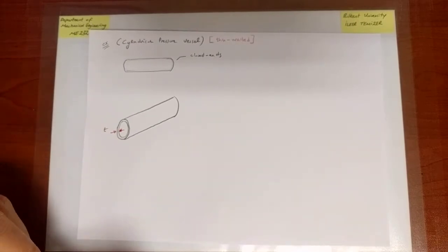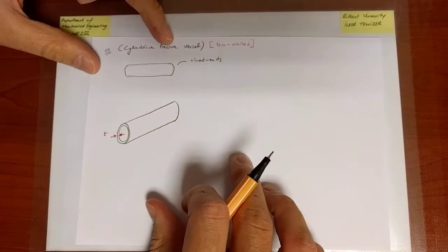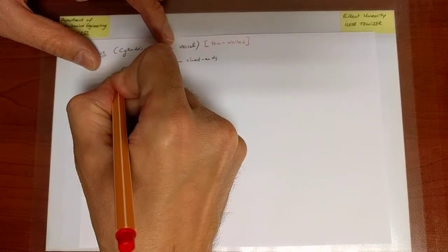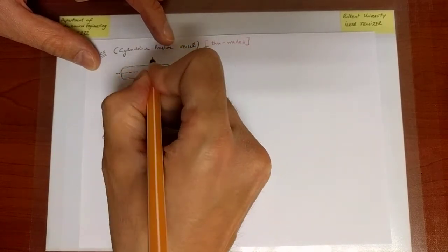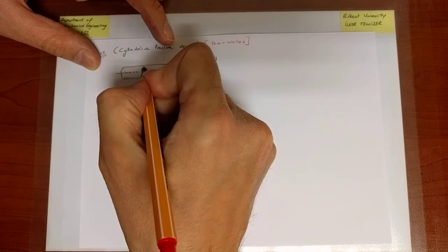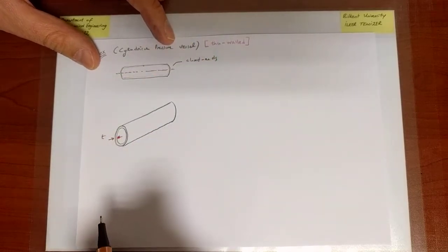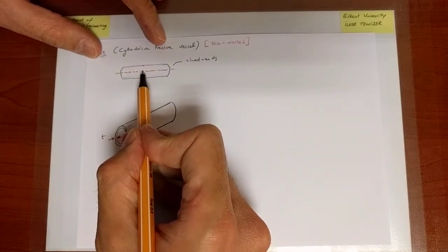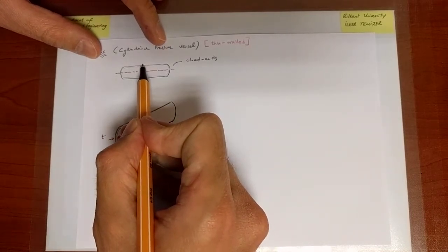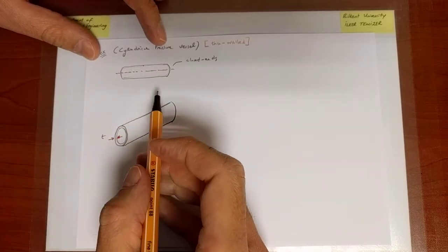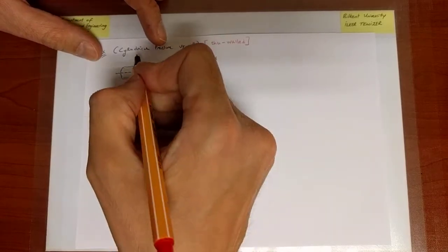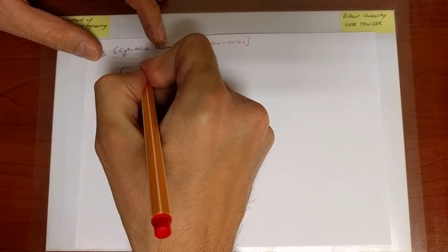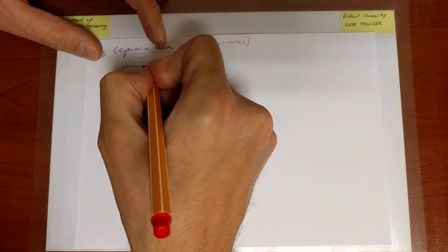And also, it is going to have a certain radius. Now, that radius is going to be the distance from the center line to the solid portion of the cylinder. Now, the distance from the inside, to the outside, somewhere in the middle? In practice, it will matter. But because we're making the assumption of a thin wall, I will often just denote a single radius value.